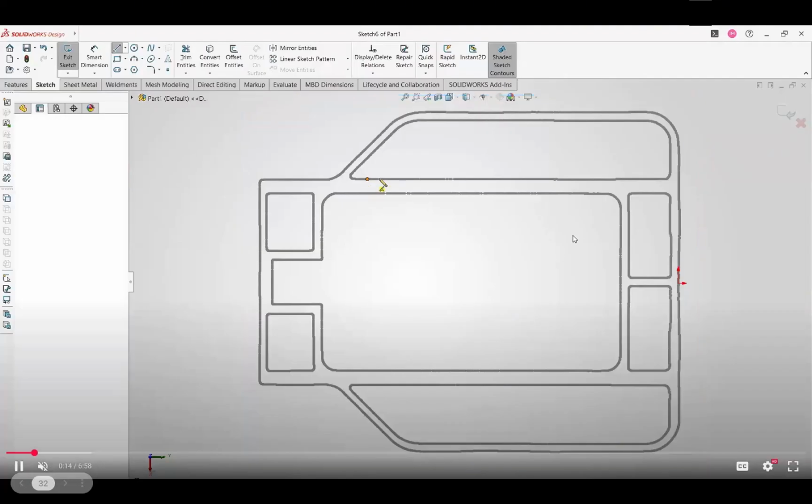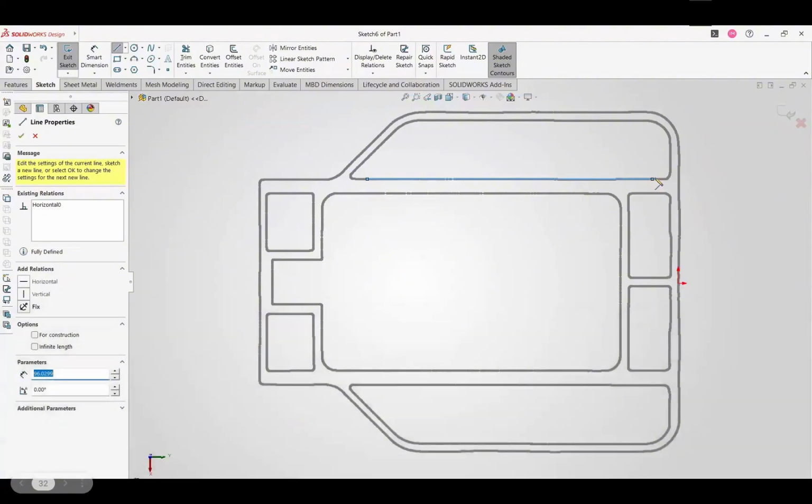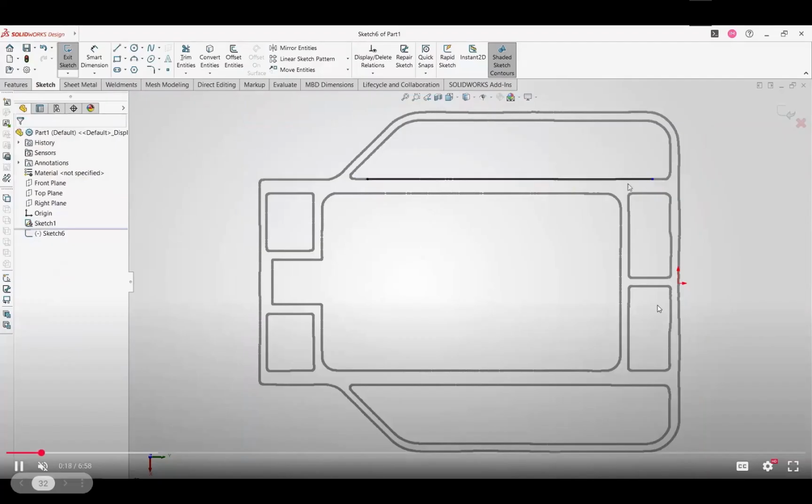What I would like to draw your attention to is the specifics of working with the sections imported from Artec Studio. Now you can see I created a line, but the line is black and the beginning of the line is also black. It means that the beginning of the line is constrained.